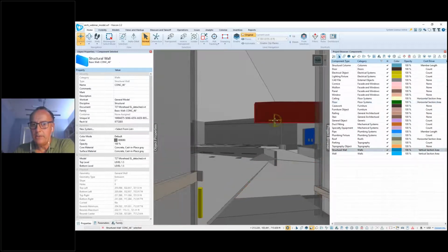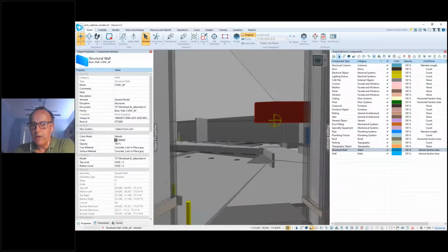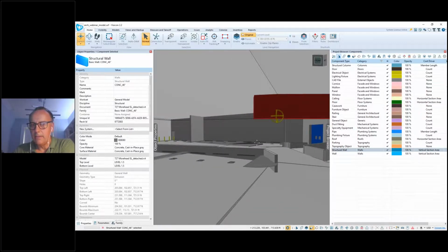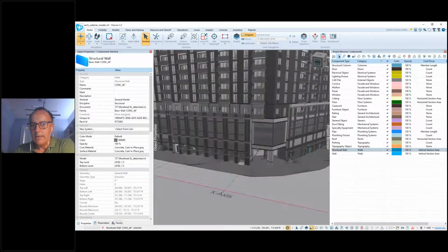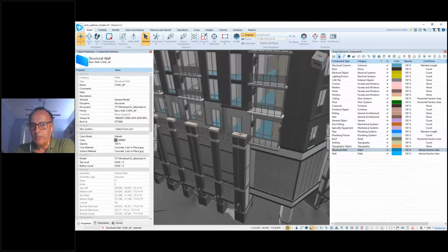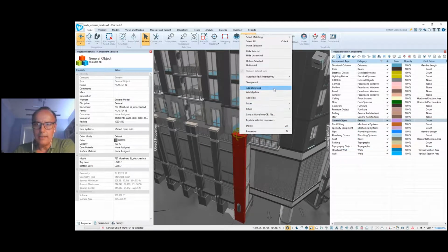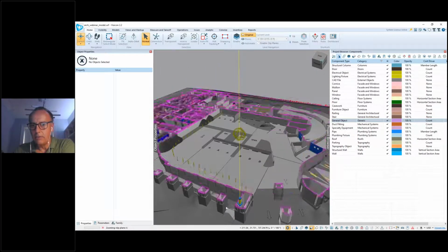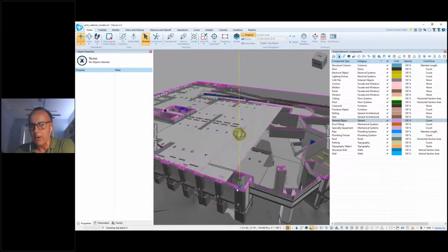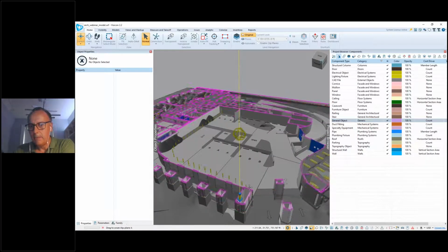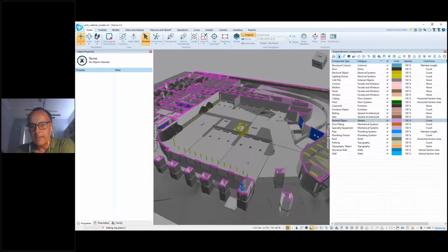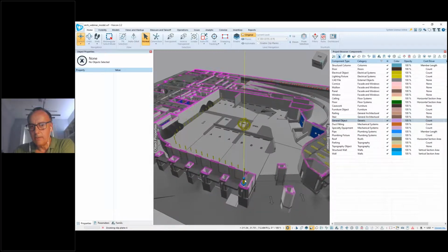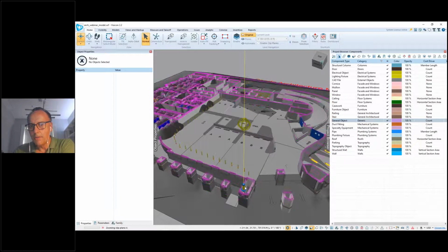Do you see that there's this transfer beam right here? And the architect clearly has not, there's some support or something missing in the architect's model. I can come in, again, similar as we did with a structural model. I'm just going to tap the top of this column, add a clip plane, and that would allow me to come in and also understand exactly how the architect has set up the space below. And I can see immediately that the architect's model is still missing some columns and supports that we need here.